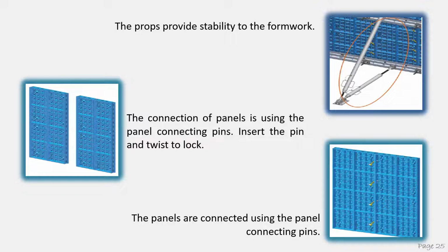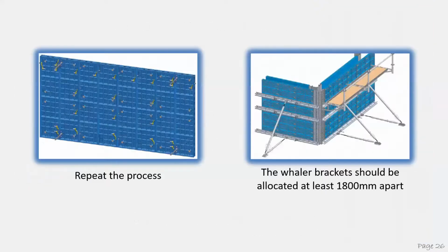So that's why you can see that the jointing ataupun the connecting pin for every each panel must be very tight enough. So that is the connections. Okay, so repeat the process. So that's why it is economic if you use for high repetitions of design. If not, you have to change or use different size of formwork, so that will cost more extra.